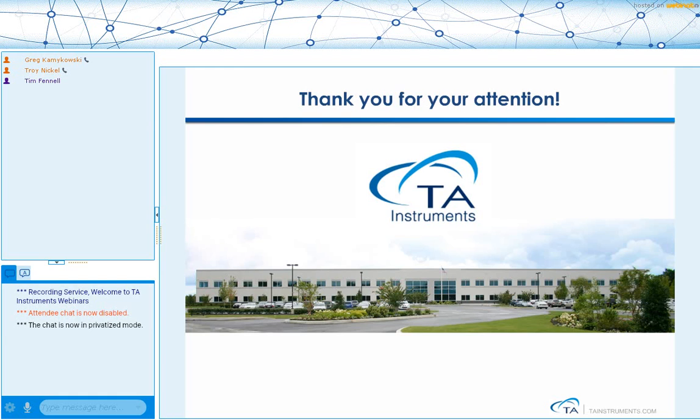Okay, thanks, Greg. Here's another question. Which geometry do you suggest for foam samples? For foams, I guess I would probably go with parallel plate compression, and in some cases what you would do would be to glue a foam to the parallel plates if you're concerned about contact or having a nice uniform contact. But yeah, I would probably do a compression test to get the properties of foam materials. That would work probably the best.